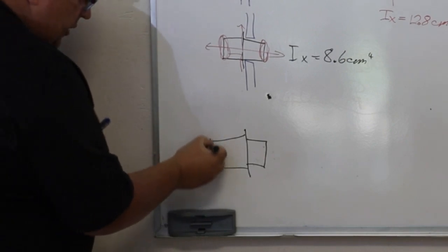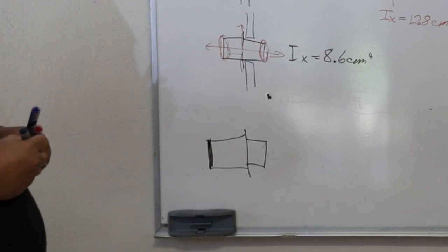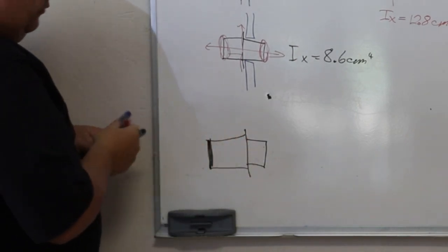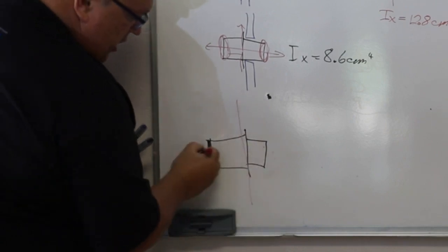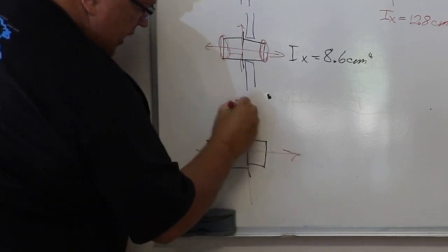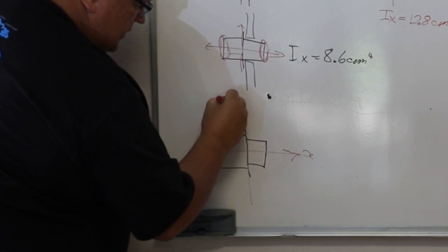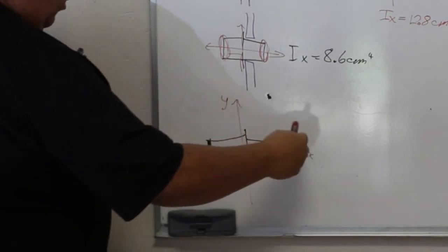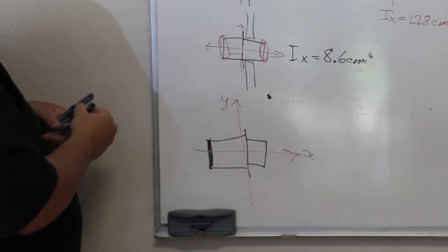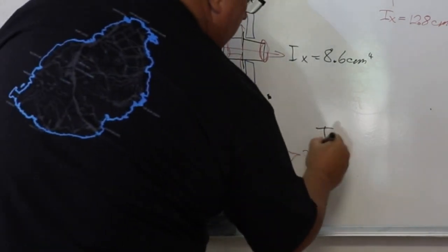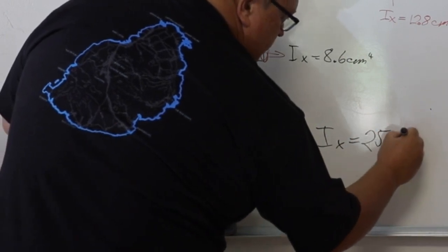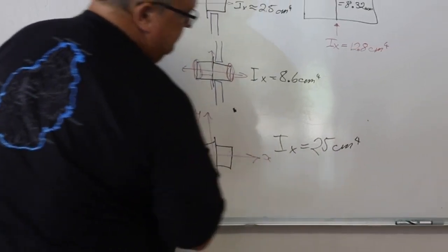And in fact, we increase this wall thickness. So now we've moved even more material away from that centroid. There I would once again have my X and my Y axis. And now on a 70 mm mullion, I've moved even more material away from that axis. So my Ix value might be something like 25 centimeters to the fourth power.